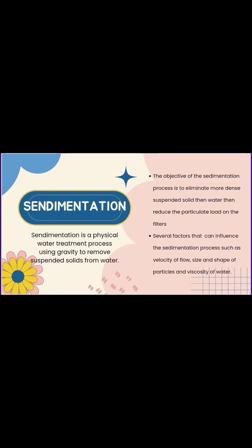The objective of the sedimentation process is to eliminate suspended solids more dense than water and reduce the particulate load on the filters. Several factors can influence the sedimentation process, such as velocity of flow, size and shape of particles, and viscosity of water.